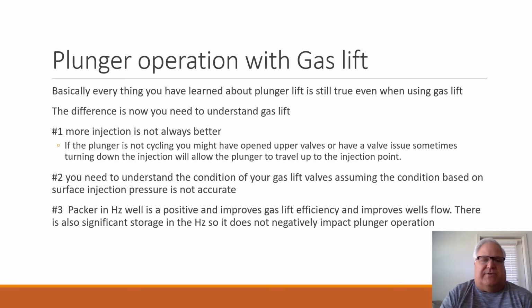But it's critical to know that number one, more injection is not always better. In fact, most times people make that mistake. If the plunger's coming up slow or not working properly, they try to jam more gas down there. Many times all that does is open up an injection point even higher, or increases some of the back pressure on the well. It is not necessarily going to give you better performance. So, don't just assume that you should increase injection. Many times you do better by reducing injection.